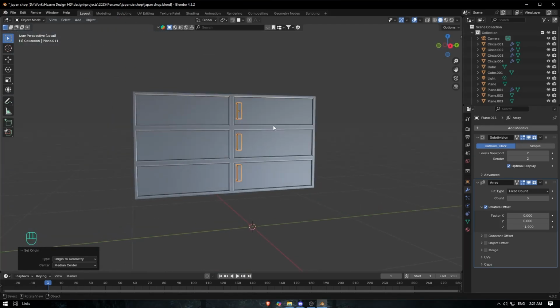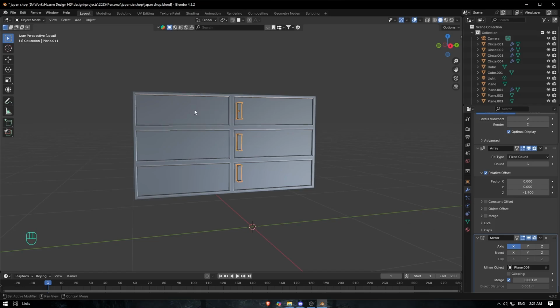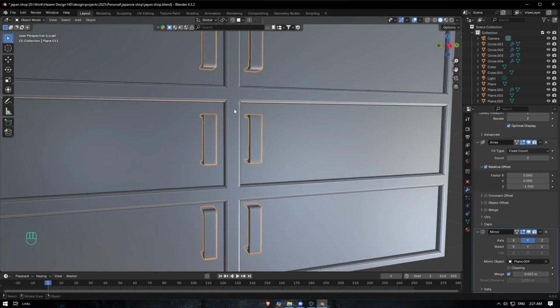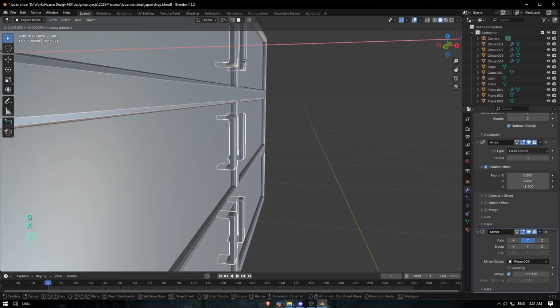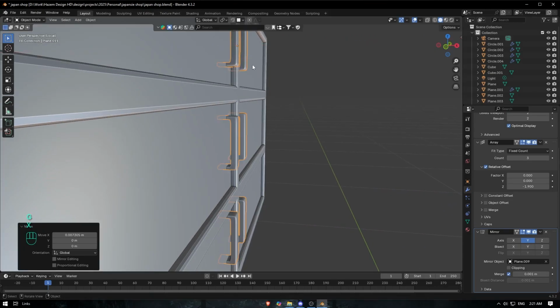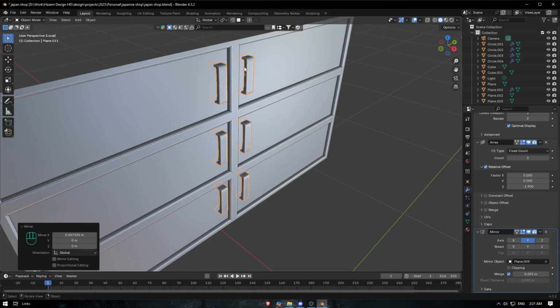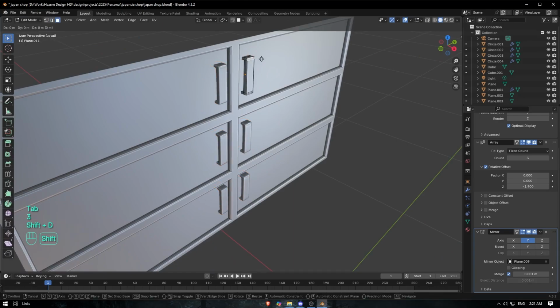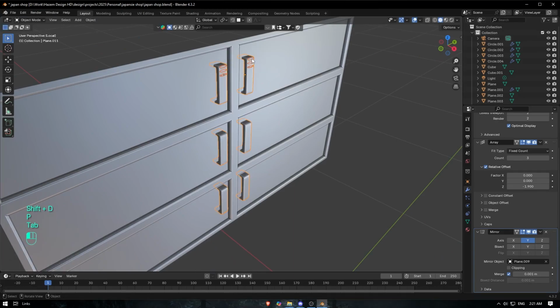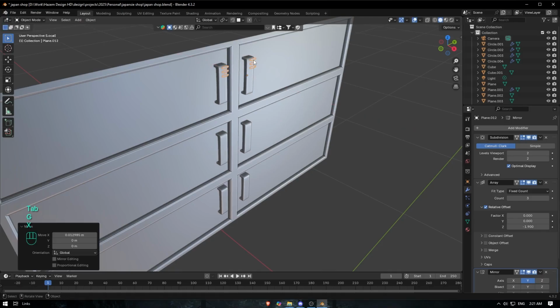like this. And instead of Alt D or copy, I'm just gonna use mirror, and mirror object, gonna pick this one and switch to Y axis, and here I think this one is done. We can move it like this, so outer inside. Maybe I'm gonna copy this one, Shift D and then B to separate it, and go here,